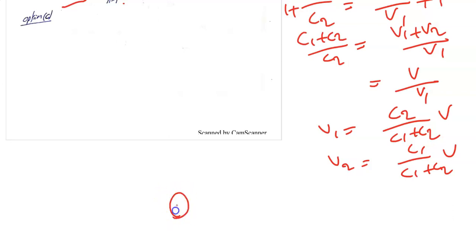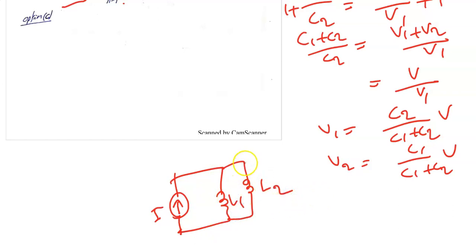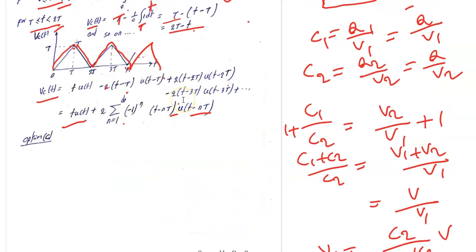Like, I can say a current source. Let's say current I through the inductors L1, L2. You need to find I1 and I2. Try it yourself, same principle. Here, for the inductors, there will be L di upon dt, or you can say the relation flux linkage psi equals L i, just as an indication. Now you can easily do it. Okay, see you in the next part.